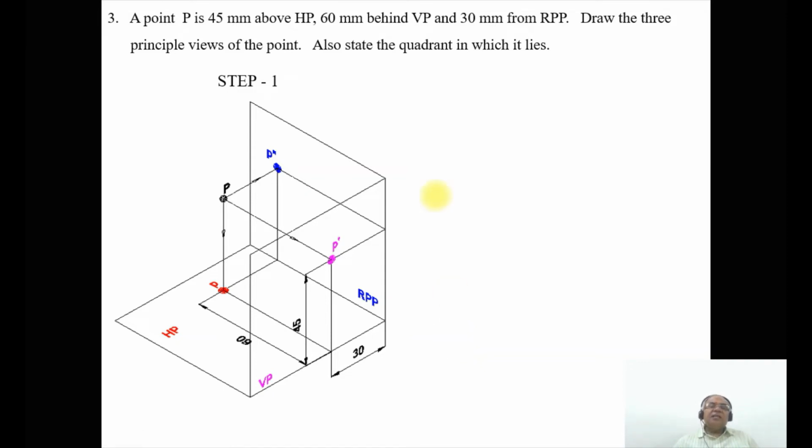So that condition is satisfied when you are looking from the right side view, because the plane is between the object and the observer. So obviously, the right side view has to be satisfied when you are looking in the second quadrant. When you look from the right side view, the object is behind RPP. Since the object is behind RPP, that distance is this.